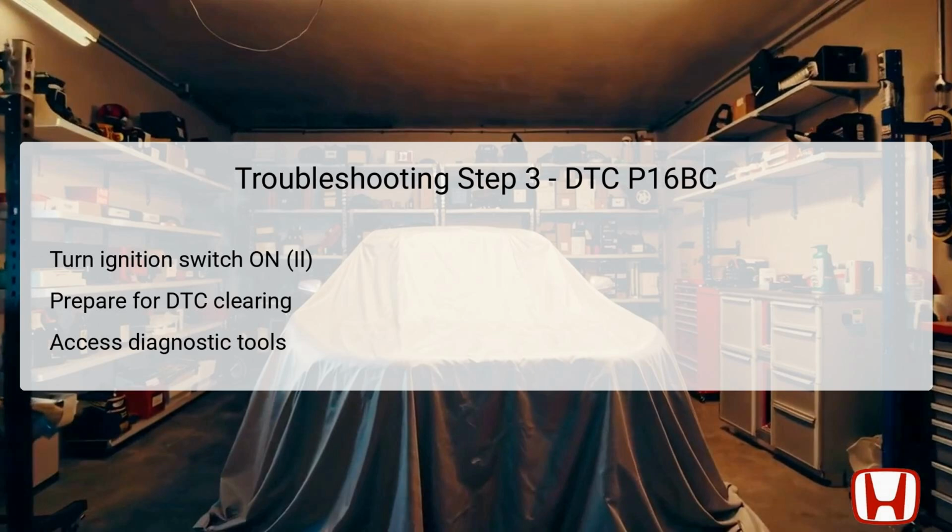Ensuring that all electrical connections are operational before this step can prevent complications. Note that the ignition should not be turned to the start position, as this can introduce confusion in the diagnostic process. Once the vehicle is in the appropriate state, you're prepared to clear any existing error codes.